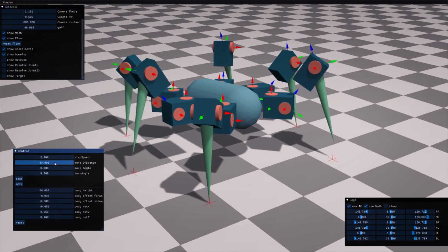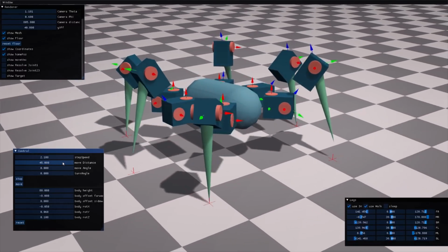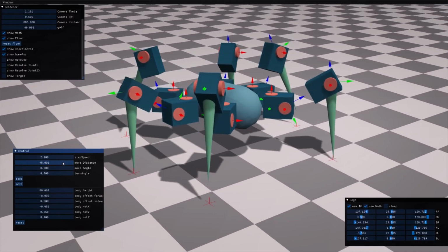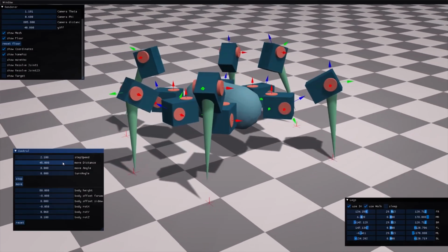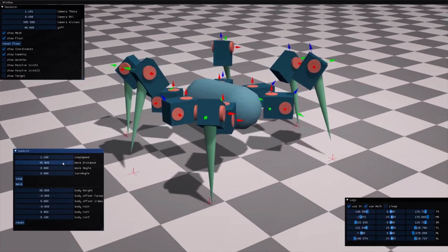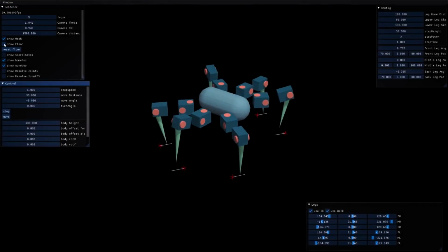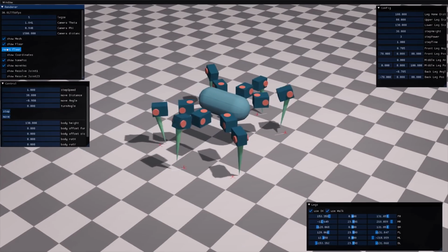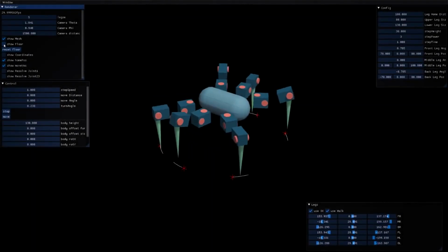Anyway, with this ready, I could try to solve the walking cycle problem. The hexapod always has 3 legs on the ground, and when it moves, you want to keep the distance between those 3 legs the same. Otherwise, it starts dragging its feet, and that's something we want to avoid. So you want to move those legs in the same direction and the same speed at any time. For moving in a straight line, you want to follow a vector in that direction, and to rotate, you want to move in concentric circles around the center point.